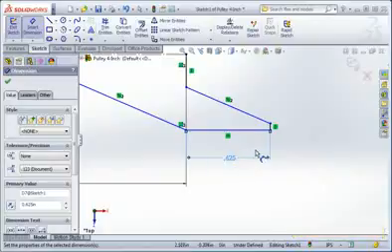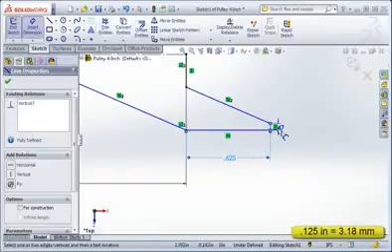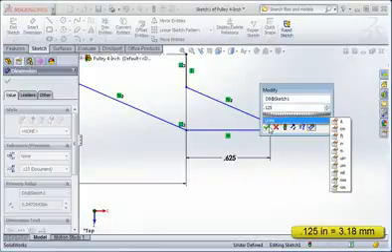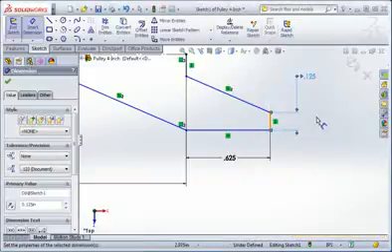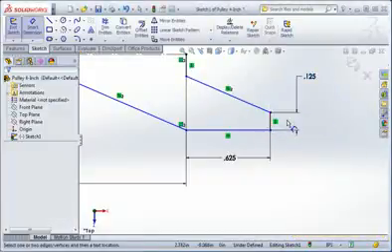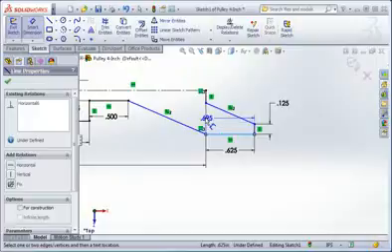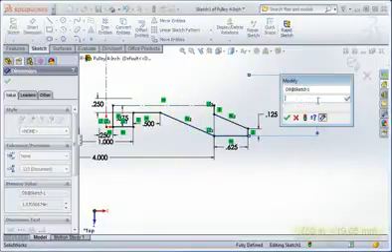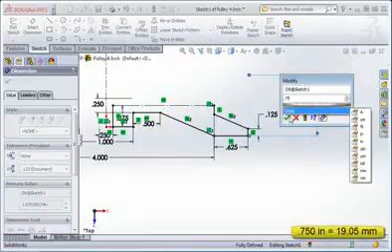We're also going to make the length of the vertical line 1/8 of an inch, so add this dimension. And then add a diametral dimension from this line to the horizontal construction line. Set this dimension to 3/4 of an inch.